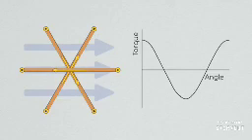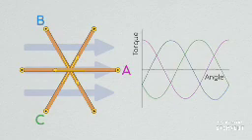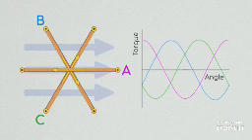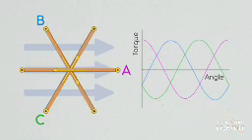If these loops are 120 degrees apart, we could plot the torque that each would produce at any point during rotation. What we see is that at any time, running current across the loops in the direction indicated by the arrows always creates a positive torque in at least one of the 3 loops. So we can make it such that each one is active for the 180 degrees where they produce positive torque, then inactive for the remaining 180 degrees. However, if we did this, we aren't taking advantage of half of the times our loops are aligned with our magnetic fields. This would make our performance non-ideal,